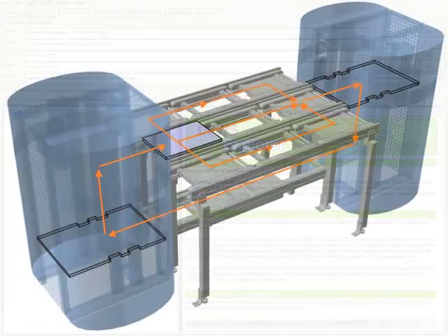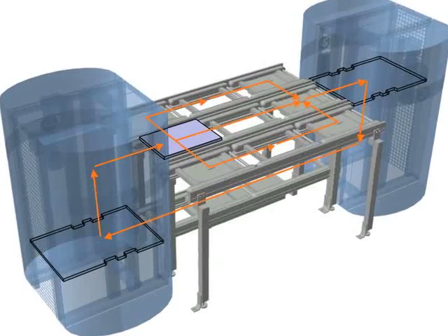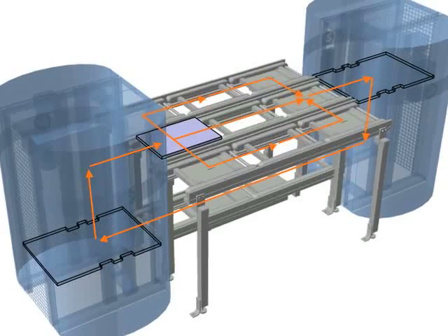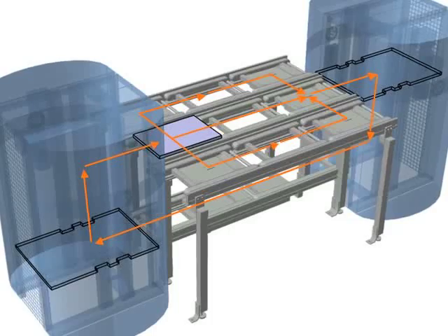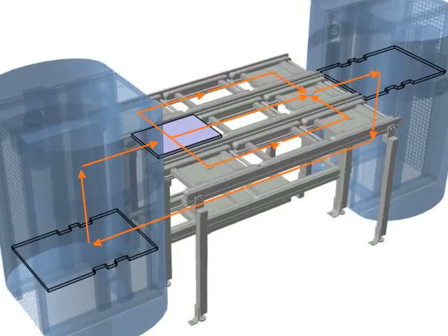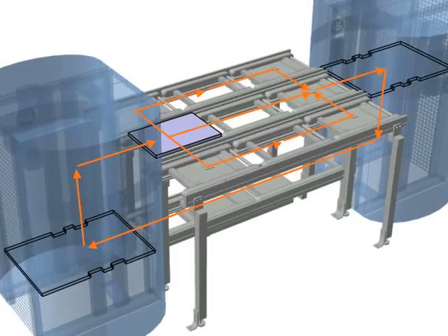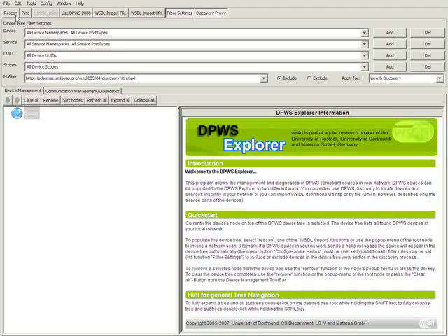For this demonstrator, we have developed a small production cell in a closed-loop configuration, which offers modularity, flexible routing, and support for external decisions. The production cell has been separated into small, independent smart devices linked to individual conveyors, switch tables, and lifters. These devices are autonomous and communicate via web service interfaces.